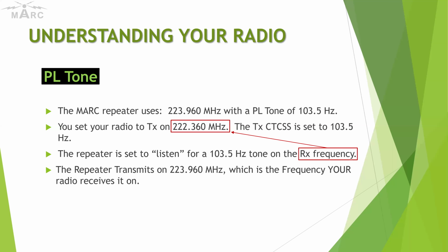I think you will. And that was my exact same question. You could put a tone on the transmit of the repeater and probably nobody would even notice. Right. If you have a transmit tone on the repeater, your HT will not open squelch if it doesn't have that tone, so you will not hear it. I disagree with that.